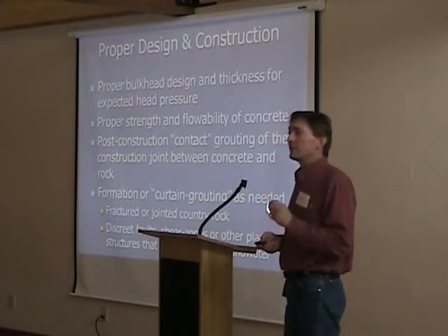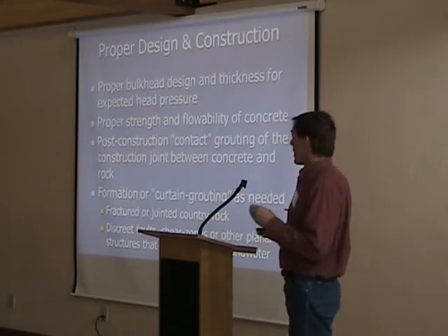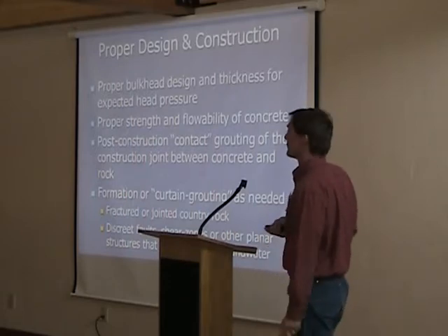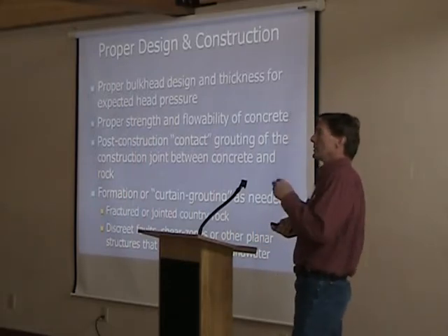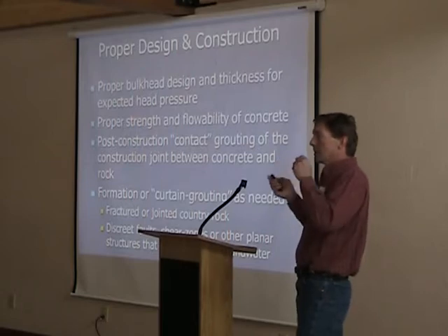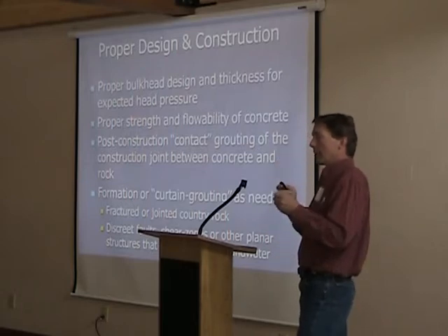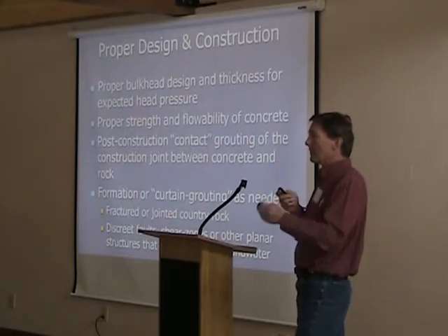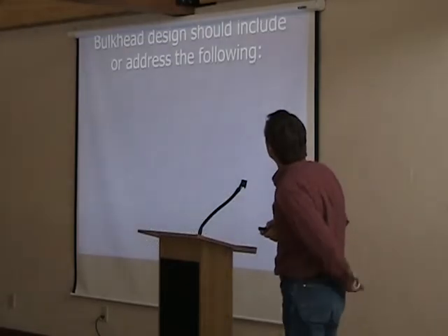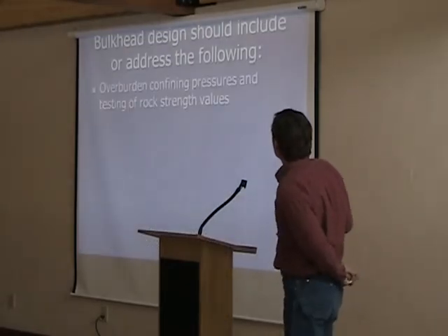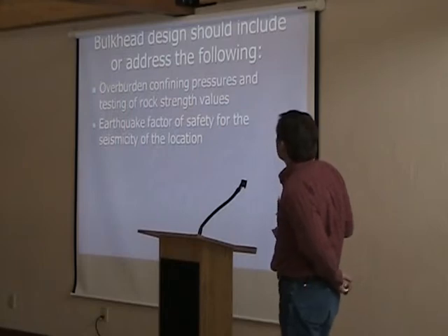And then in some cases, if you've got a lot of fractures and the rock isn't as good as you would hope, then you have to do this formation or curtain grouting, which is like what we did up at the Kohler, to kind of try to increase the bulkhead performance by filling up some fractures and cracks. So I'm going to show some other factors of safety that go into this.